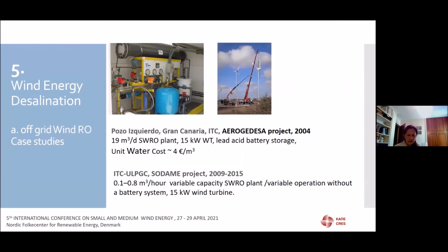Other cases are the wind RO systems developed by ITC in Gran Canaria within the Aerogedesa project in 2004 and the Sodama project in 2009. The project concerns the matching of a 19 cubic meters per day seawater RO plant driven by a 15 kilowatt wind turbine with and without battery storage. Finally, the Sodama project results validate the need of energy storage and constant power supply for the RO unit.